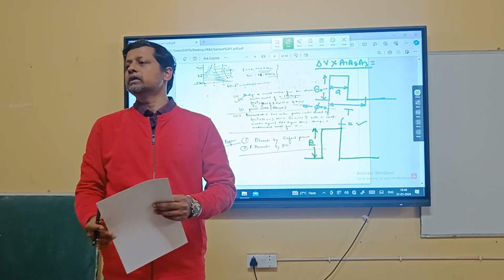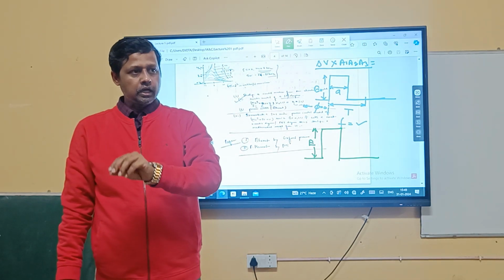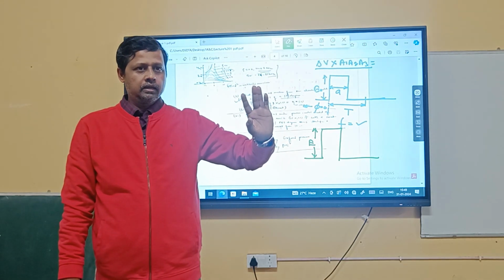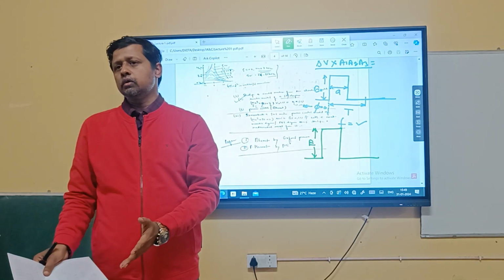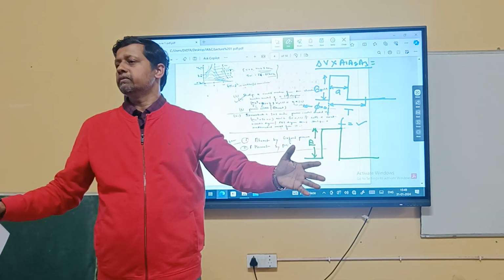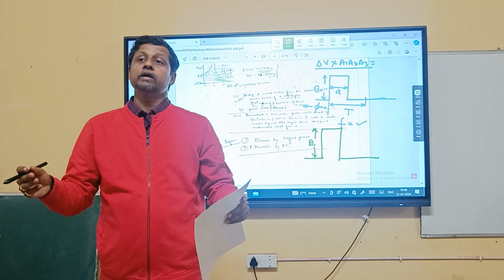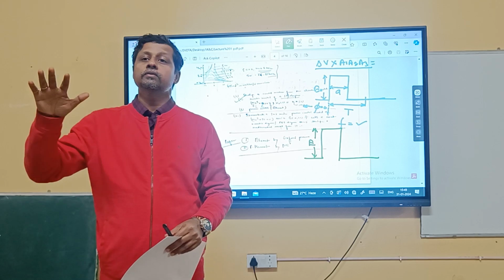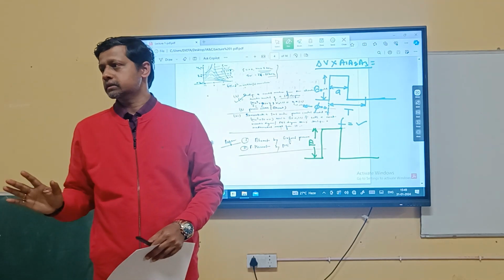Then it is transferring to the controller. Now the controller is maybe 500 meters away, maybe 2 kilometers away from that field device. Okay? Now you want to propagate this data from this point to 2 kilometers away, maybe to your house. Is it a very far distance? No. Do I need modulation? If I don't require modulation, I don't require complementary demodulation also. So if I don't require these cumbersome devices, can I cut down my cost? If more devices do not get involved, am I not reducing the chances of failure of the system also? The more devices participate, the higher the probability of failure.